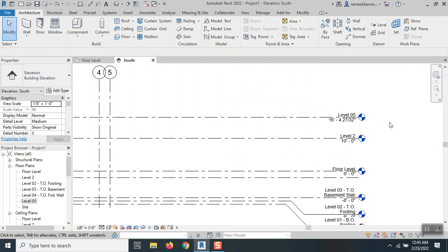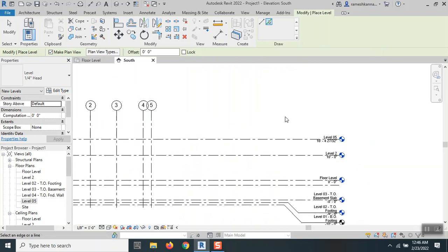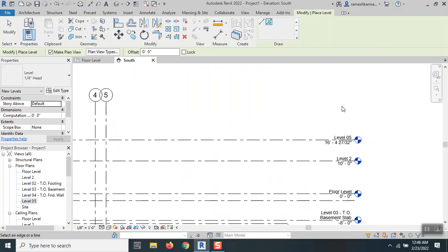So it's automatic, right? So there are only two things in the level: just the copy, this is the line creation, and then the pick line method. Pick line method is what pretty much every student likes, because it's pretty easy, and it is used when you know the offset, like for example, the other floors, like level 6 and 7 will have a predefined thing. Say for example, the next floor will be like 10 feet, right? So I give an offset.